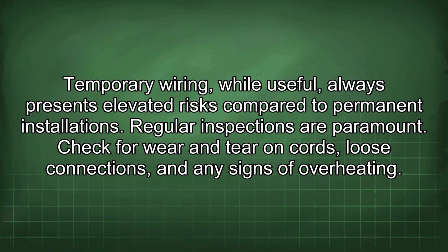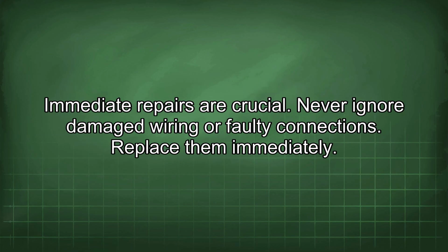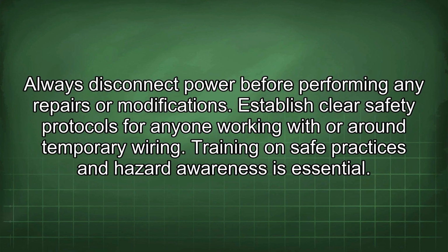Temporary wiring, while useful, always presents elevated risks compared to permanent installations. Regular inspections are paramount. Check for wear and tear on cords, loose connections, and any signs of overheating. Immediate repairs are crucial. Never ignore damaged wiring or faulty connections. Replace them immediately. Always disconnect power before performing any repairs or modifications.